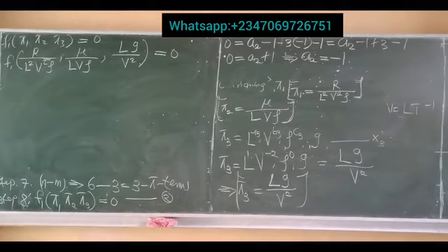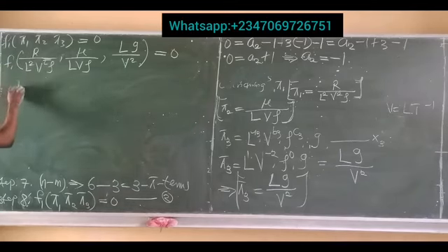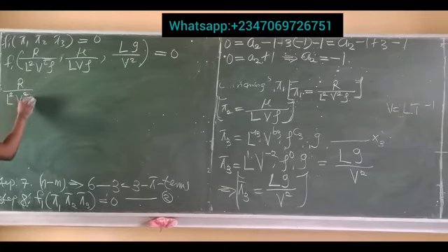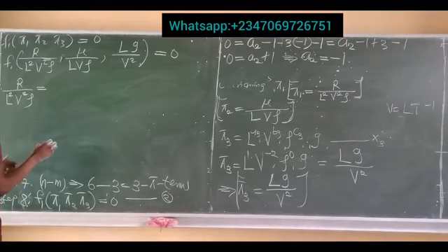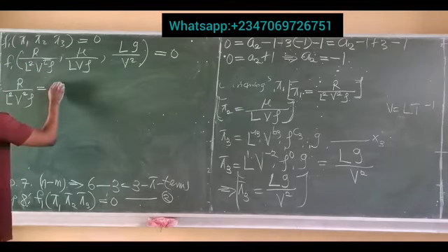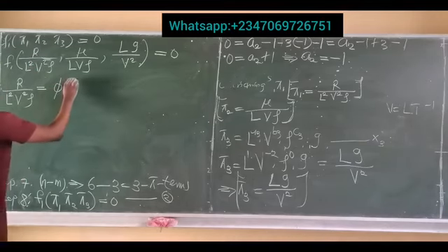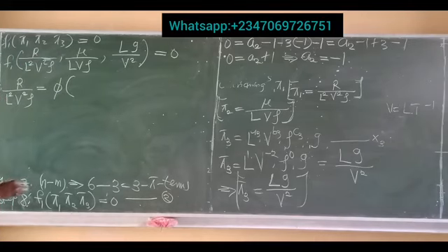Now be very careful at this point. We are solving for a term of R from the question. Remember, write a dimensionless expression for R. So remember that R was the dependent variable. So you pull out R from this bracket. You're going to have R all over L squared V squared rho equal to, mind you, immediately you pull out this R over to this side of the equation, you introduce this function F, and the bracket will take a different order.